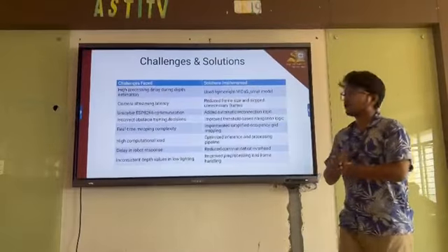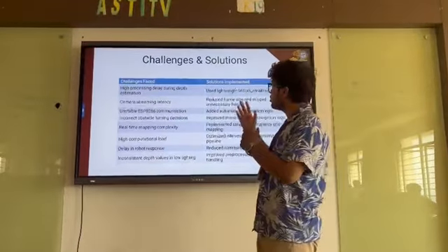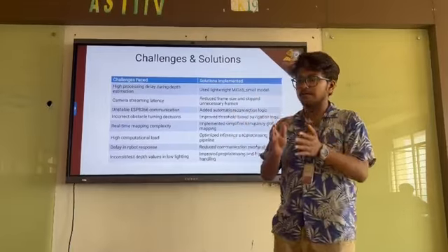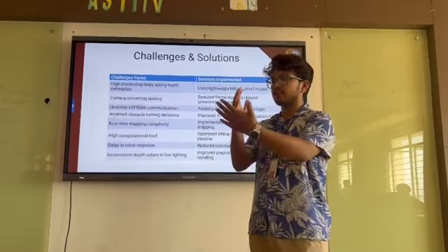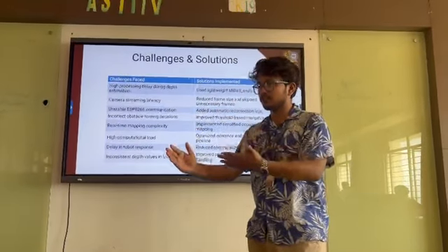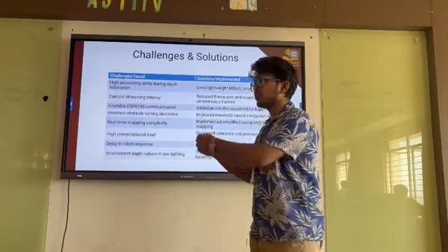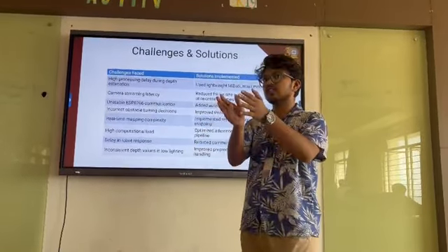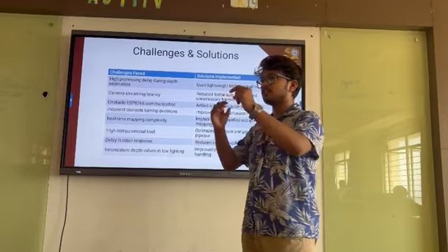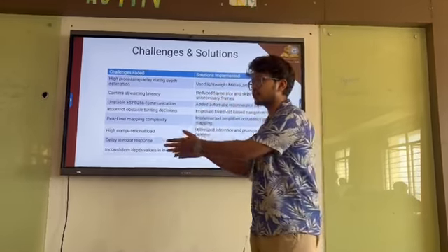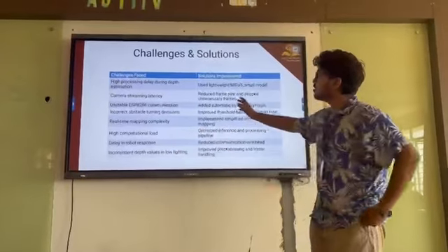Thank you, Vaibhav. Coming to the challenges and solutions, as we see how the model is going to work, when the car moves, the model will detect the depth, brightness, and the dark spots. If there are dark spots straight ahead and on the right corner, then it will take a left turn where the brightness is high. So it is a rule-based model in which it will see where the brightness is more. From that direction, the car will turn.